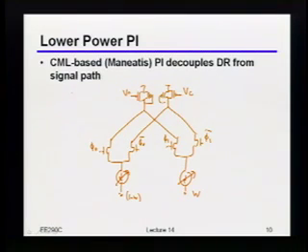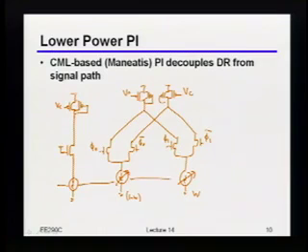So the way we build that replica bias is going to look something like this. I just take the same resistor structure with the same control voltage. Then I'm going to take something called the half buffer replica, meaning it's like taking half of the circuit configured in a static way to mimic the swing you're actually going to get. So I'll just draw that. And then, of course, I'm going to have my current source down over here. By the way, that current source would be an NMOS transistor, but I'm just drawing it as a current source for clarity for now.